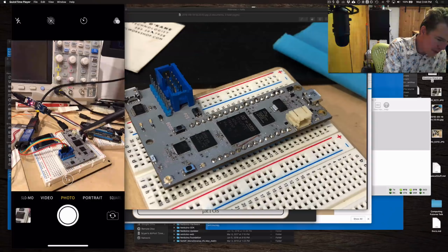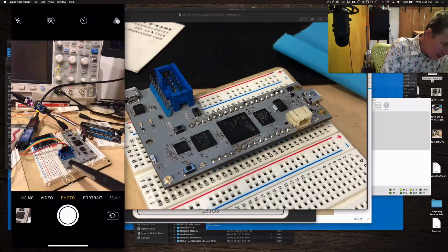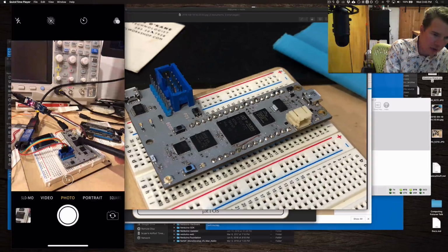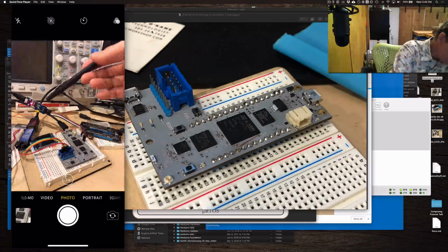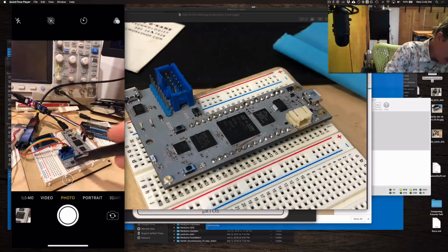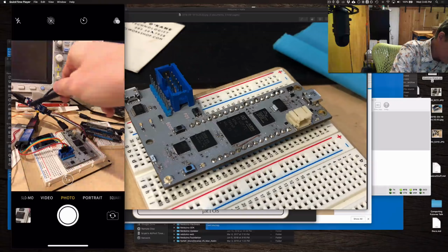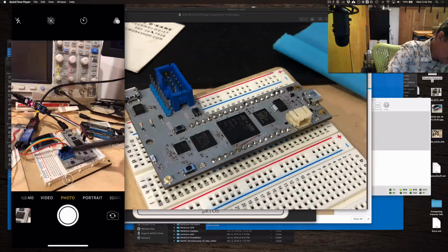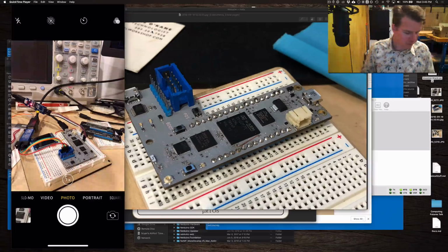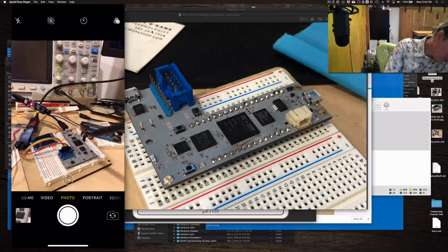And then we have serial debugging, and that one is actually supposed to come out over here. If you look at this, there's a USB adapter here, and then there's this little chip that hooks up to serial on the microcontroller. Everything on this board is basically in this little section right here. There are LEDs, tiny LEDs, and this FTDI chip which converts serial to USB.